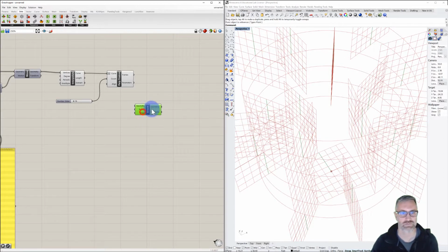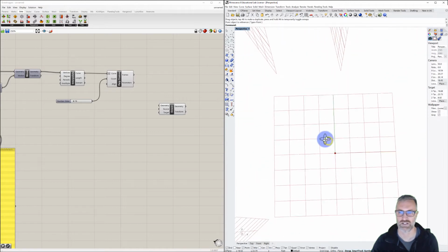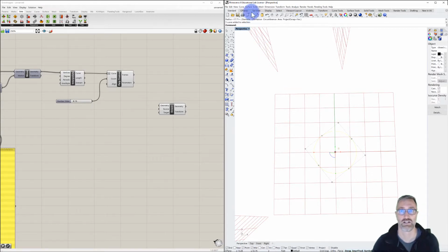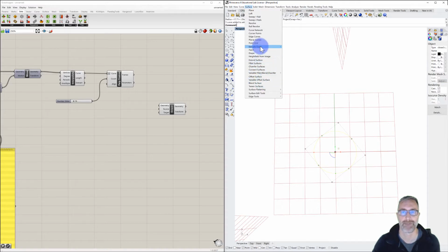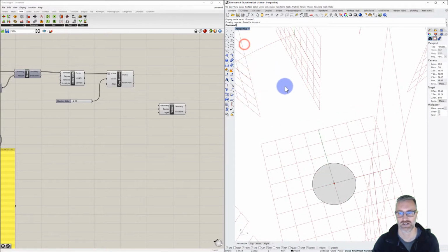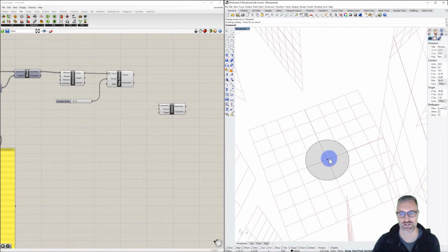And so we're going to take geometry. Let's just try this with something very simple. Let's start with a circle here. Let me make it, let's see, we'll do surface. I just want to do planar curve. And ghosted. So now we have just a simple circle. The circle may not be great, we'll see this in a second, because of its orientation, but let's set a container for brep. And we'll set one brep to be that planar surface, and we'll plug that into geometry.